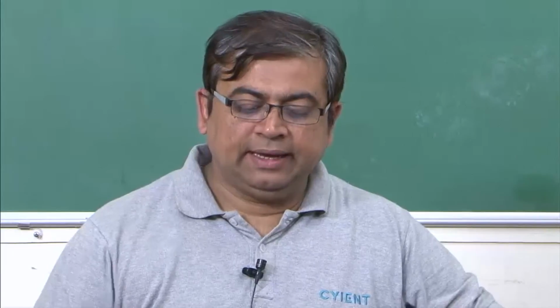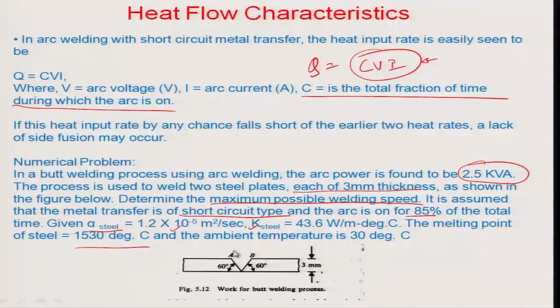So, if we go back and have a look at this weld here, the overall distance AB is this distance right about here, and this comes out to be equal to twice root 3 for obvious reasons, because this right here is 30 degrees and this is 3 mm. So, automatically this particular length can be determined as 2 root 3.